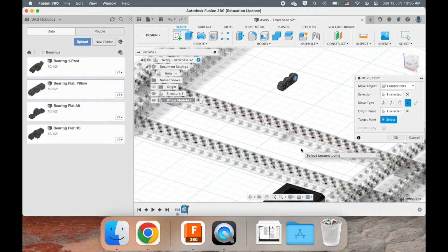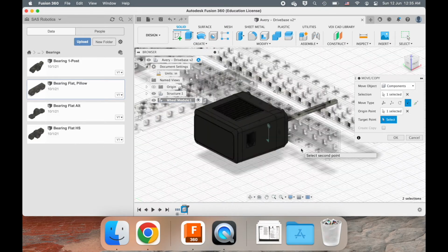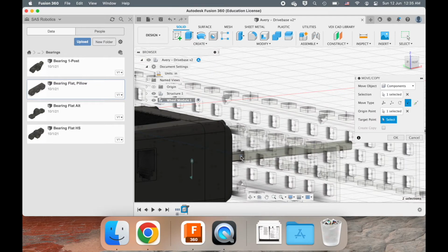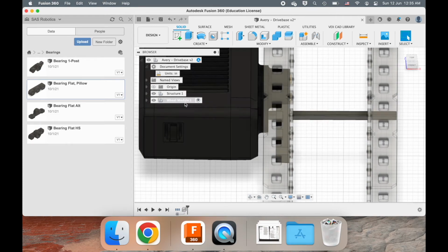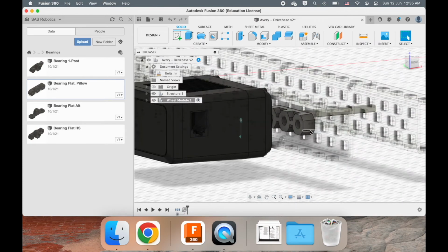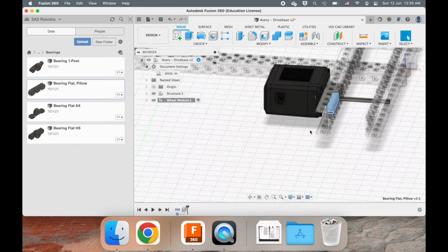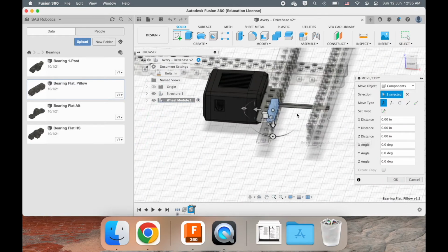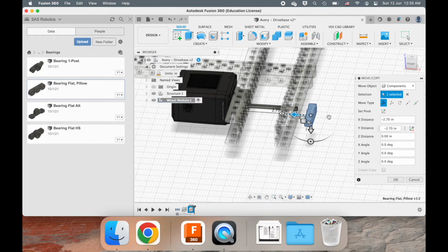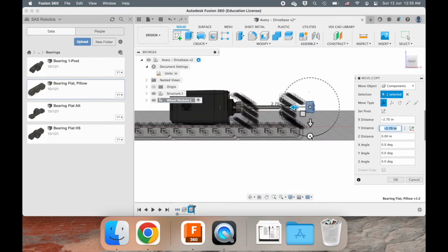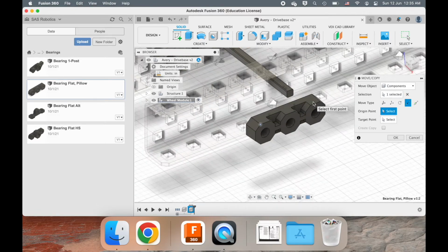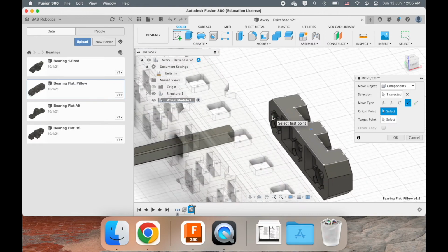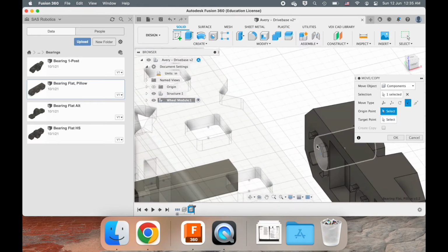So I just rotated the piece, right, and I switched to point, and then I can put in the bearing flat over here. Okay, and it's in the wheel module component. Bearing flats you almost never modify, so I can just copy paste it, right? Not going to use the modify tool on it too much. I don't think it would even work. I mean, there's situations where you might cut off one of the holes of the bearing flats just so that it can fit in some kind of tight place, but that's not the case here.